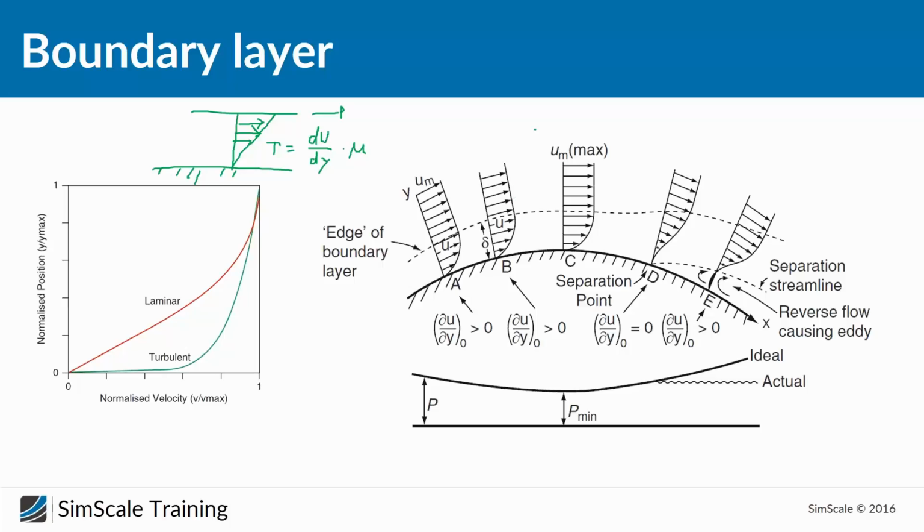And now it's very important to understand two things. The first thing is more or less related to the left image. First of all, we have to realize that a boundary layer can be laminar or turbulent or in between. I remember in the first session we had some questions regarding turbulence, and some people were mixing up laminar and turbulent because it's used a lot to describe the overall flow. You can have a laminar or turbulent wake, but you can also use it to talk about the boundary layer. And in the end, the boundary layer is laminar, turbulent, or in between in a transition.